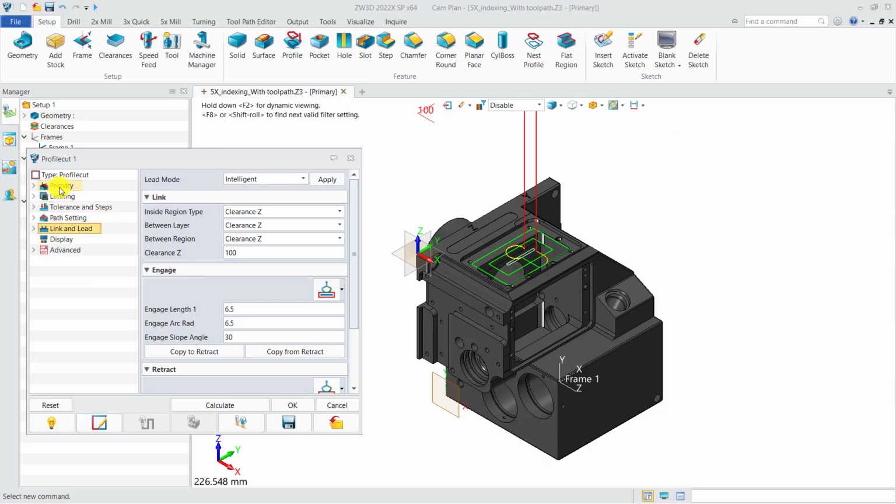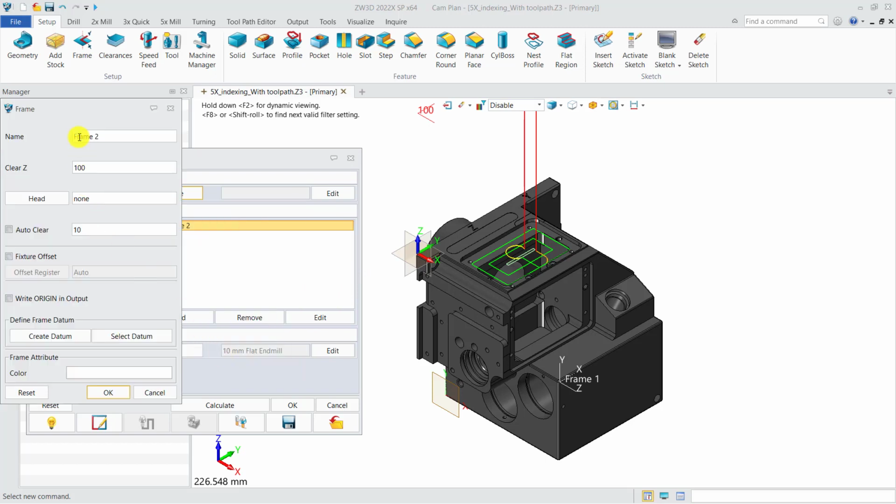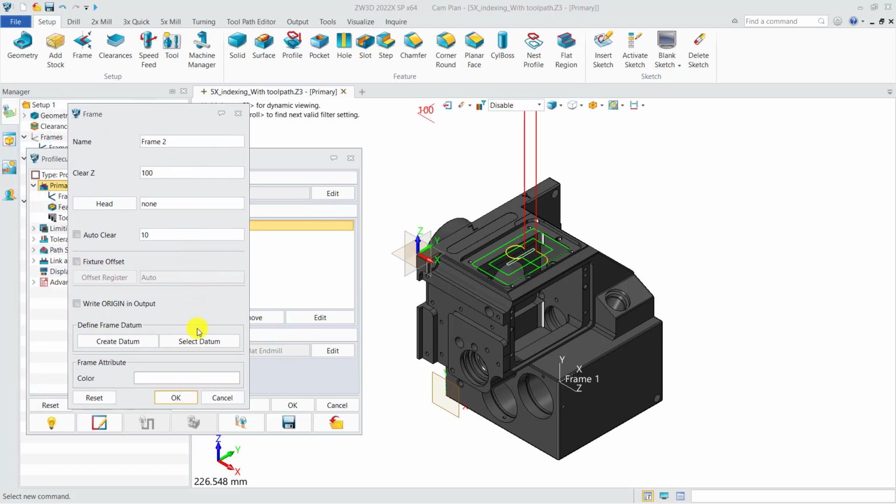These are the common parameters listed in the dialog box. So we go to the first tab in the dialog box. Frame is to set the custom coordinate system to calculate the 2x paths. None means using the default system, which is the world coordinate system. There are 2 ways to create a custom frame. You can click Manager to open the frame dialog box. The datums created in the CAD environment will be displayed automatically in this step.